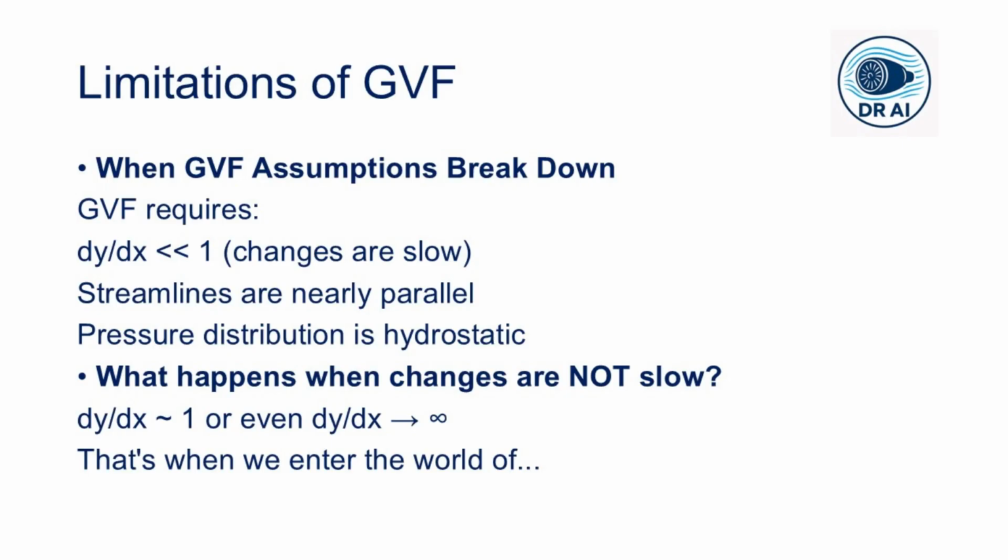Now, also think about a sluice gate where the water flows under the gate at a very high velocity with a very shallow depth. Immediately downstream, the flow might be supercritical, but further downstream, if the channel slope is mild, the flow needs to return to subcritical conditions. If it can't do that gradually, it has to do it suddenly, violently, through a hydraulic jump.